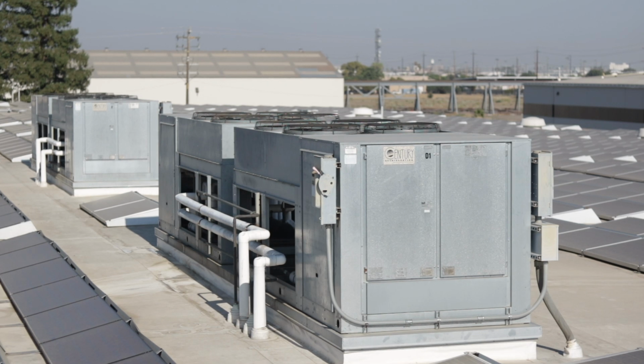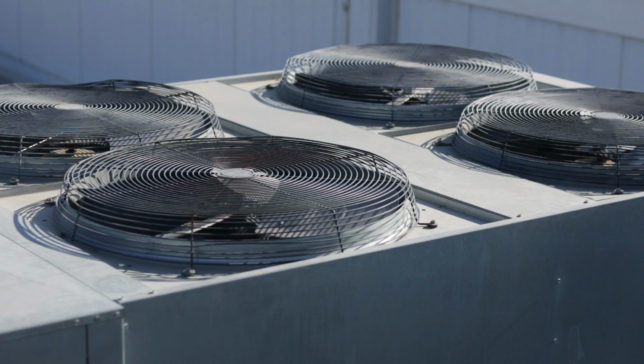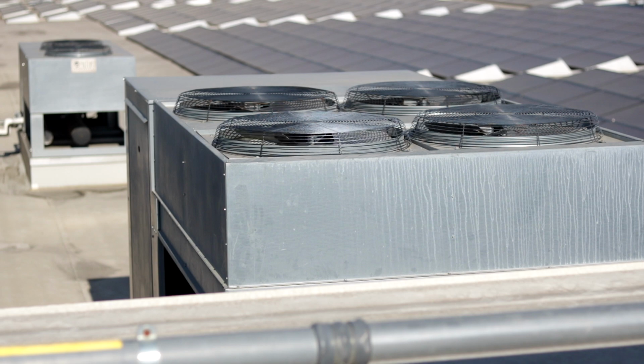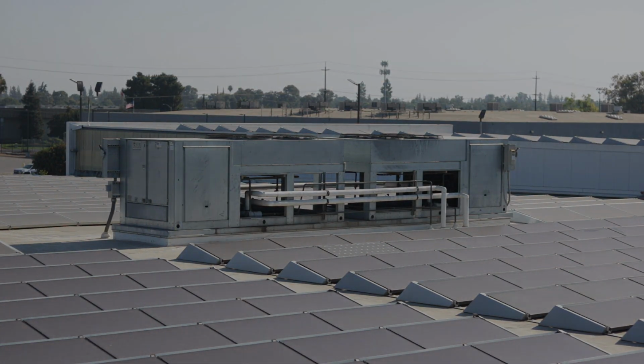Air-cooled condensers are the simplest type of condenser and use fans to move air over the condenser coil's surface. No water is employed in an air-cooled condenser. This results in the highest condensing pressure of the three categories. Historically, air-cooled condensers have been limited to residential and commercial refrigeration systems, but are gaining popularity in low-charge ammonia systems because of their simplicity.